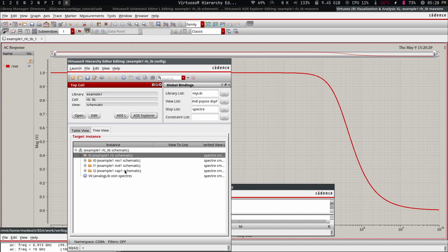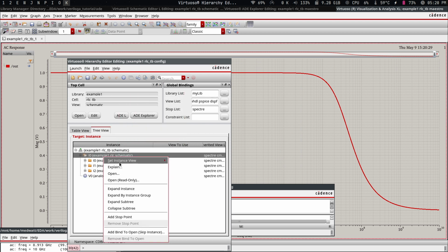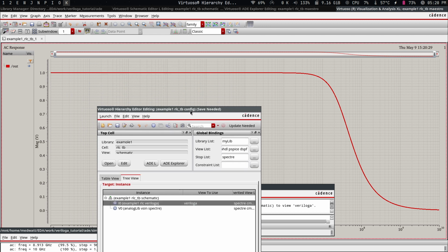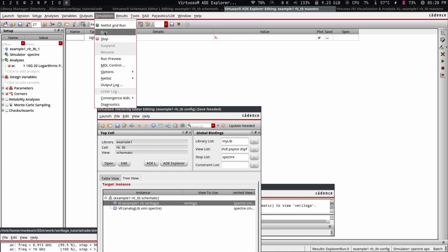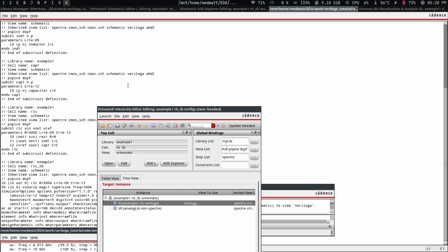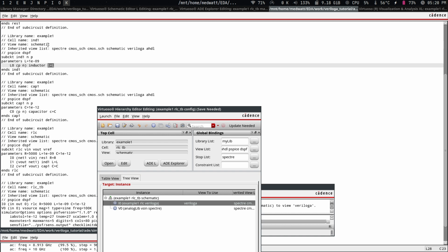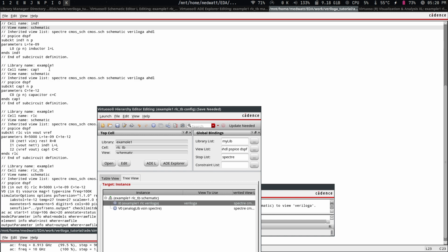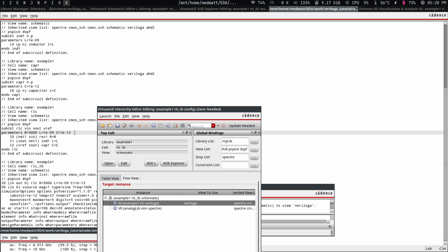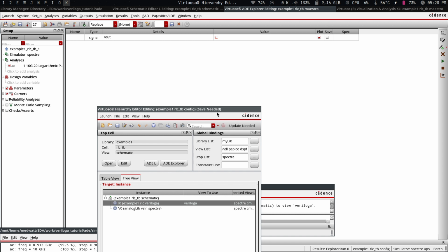Very good. So now if we switch to the Verilog-A view, first of all, let's see the netlist that was created here. Display. Okay, very good. So you can see here that all of those values, the p-power that we had provided, it's now, if you know anything about Spice, you know that they have this way of indicating when you're passing things down. So you see now that we are passing these values directly down. But anyway, let's just confirm that we are doing the stuff correctly.